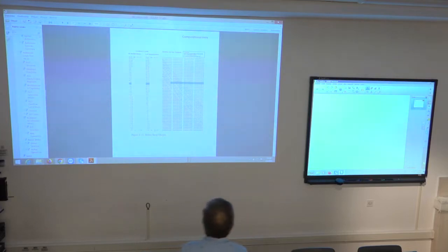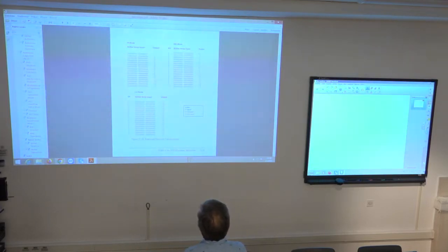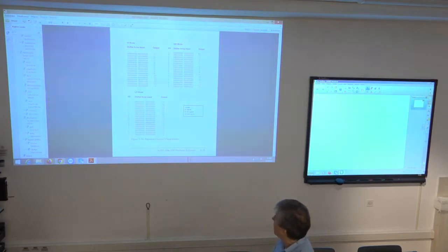Okay? And then they describe two cases, whether it is arithmetic shift or logical shift. In this case, it is an example of how this exponent detector works. This exponent detector is the first instruction that is used to find the leading number of zeros or ones based on the sign of the input value. If this input value is positive, so the first bit is 0, then this exponent detector counts how many leading zeros you have in the input register. And this value is then stored in this SE register.